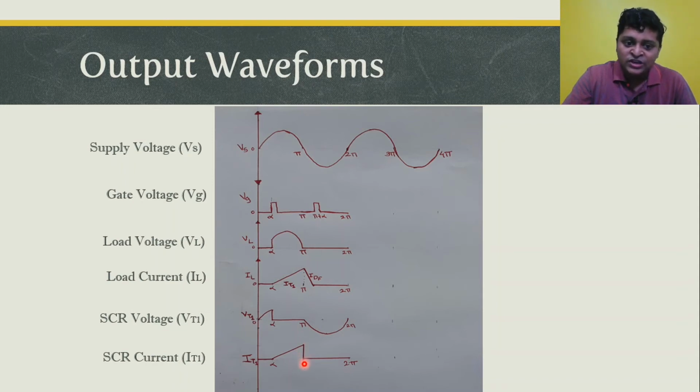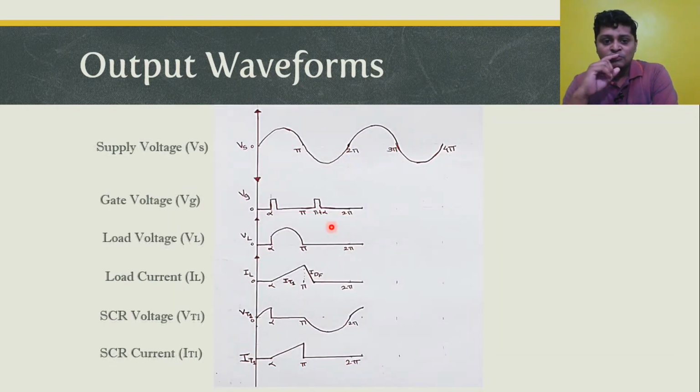The thyristor current immediately reduces to zero or decreases below its holding current value. Also, as the freewheeling diode is in forward bias condition, it applies a reverse voltage across the SCR, forcing it to go into off condition. So the freewheeling diode applies a reverse voltage, forcing the thyristor T1 to go into off condition. At this particular point, the thyristor goes into off condition. Now even if we apply a gate pulse during the negative half cycle, the SCR does not go into on condition. So let's again go for the positive half cycle.